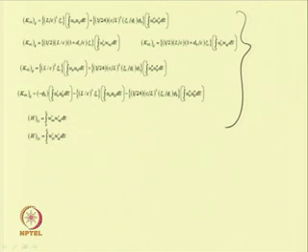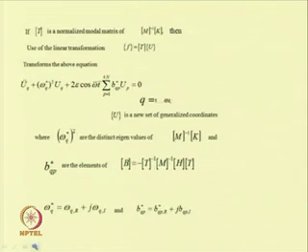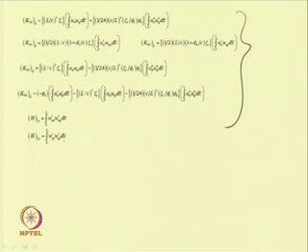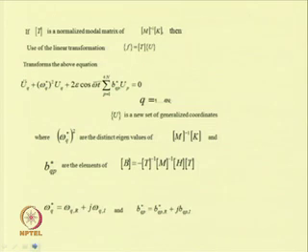So, here one has to note what the expressions for W_t and W_b are, and the expressions for these phi terms one has to see. These expressions are obtained from the eigenvalues of the corresponding boundary conditions. After getting these coefficients, one can find the mass matrix and stiffness matrix by integrating these terms, and then find the T matrix, known as the dynamic matrix. So, T is the dynamic matrix which can be written as M inverse k.